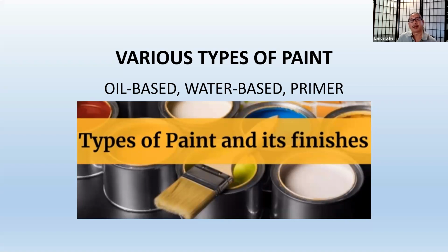Now, be aware that in the industry, there's salespeople who say that there's self-priming paint. In other words, the directions say you don't need to use any primer. You just use this finish paint, and it has built-in primer. Okay, well, that could be good, but be aware of the situation where it says self-priming, but you don't need to clean or power wash.